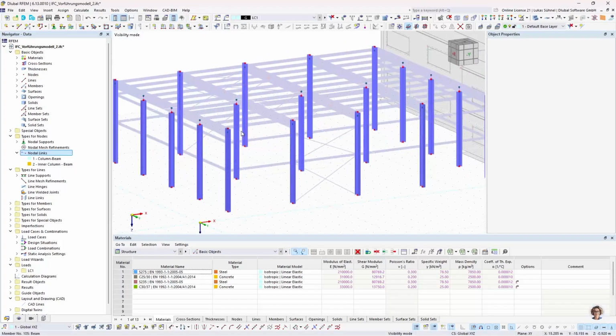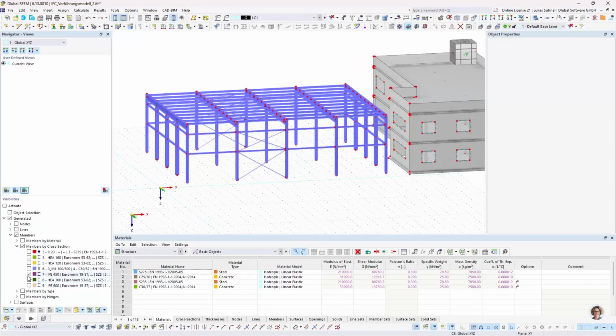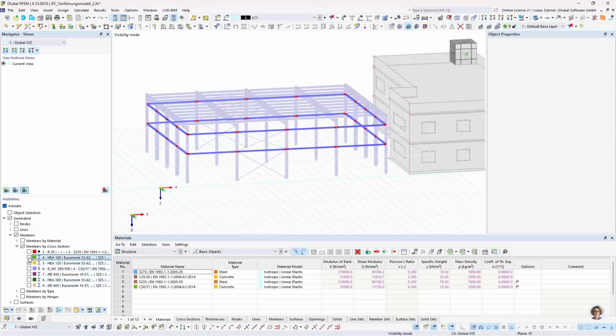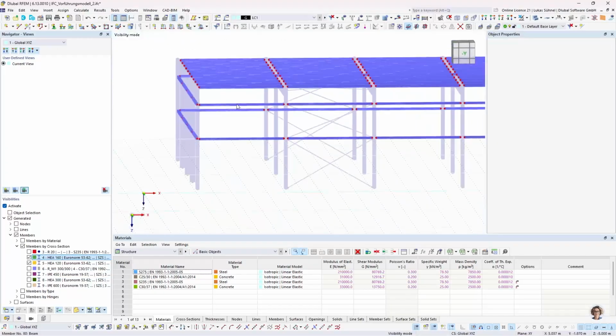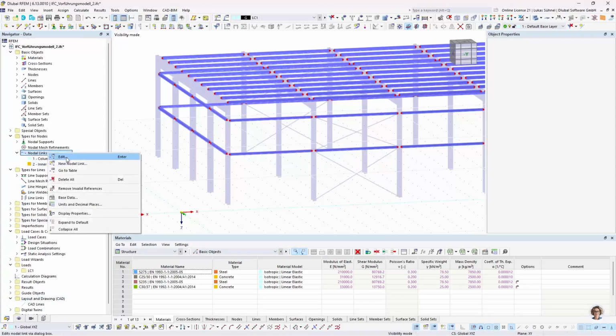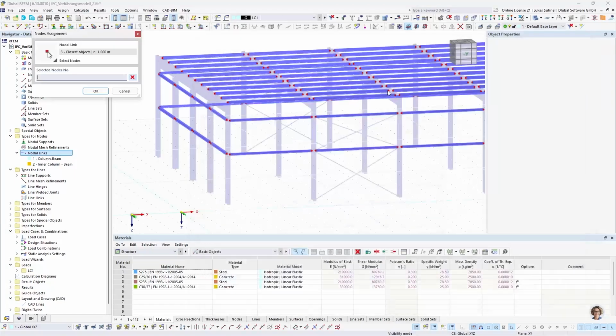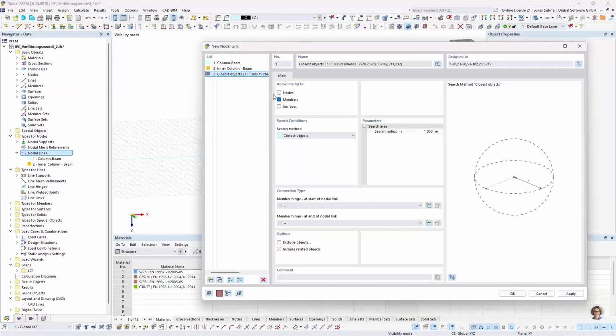So now they're also connected. And in this way, we can continue. And I want to do it so you can see maybe some obstacles that we will also face in here. And the next one will already show one of these little obstacles. So let's say we want to connect all the coupling members from my structure, which is between my frames usually. They should be connected to the columns and so on, and to the main beam. So another node link. I skip the renaming now. I think it's clear how it's working. So I select all of those nodes. And again, I say, please look for members close by. And maybe use a hinged connection.